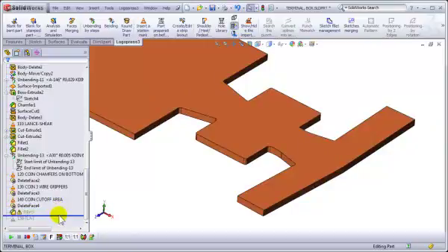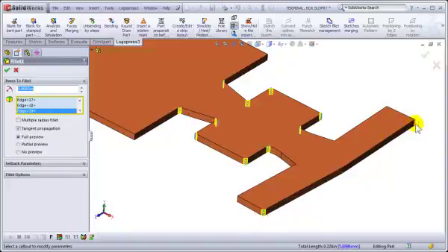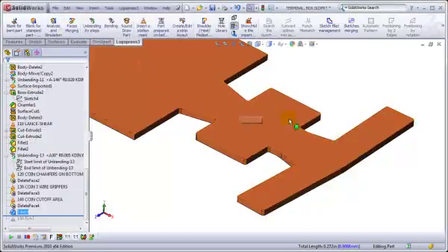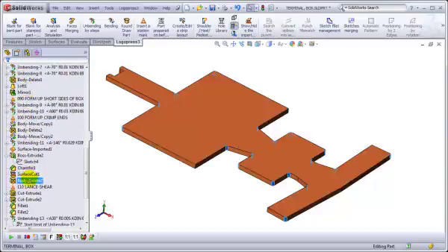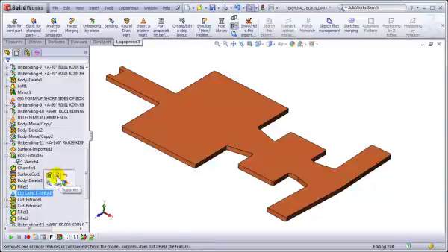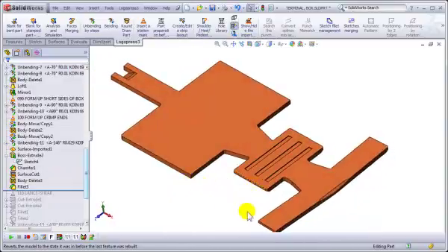And finally the fillets, and we know there will be a problem with the fillets. They're edges that don't exist because we had cut that away, so it doesn't recognize the edges anymore. And you can see by these red lines where the fillets were. There we go. And now some of them were missing, so yes, say validate that. Now let's take these fillets, and actually they ought to be higher up in the tree. So we'll drop them right there, and then they'll show up later on in the part than they would have before if we would have left it at the bottom.